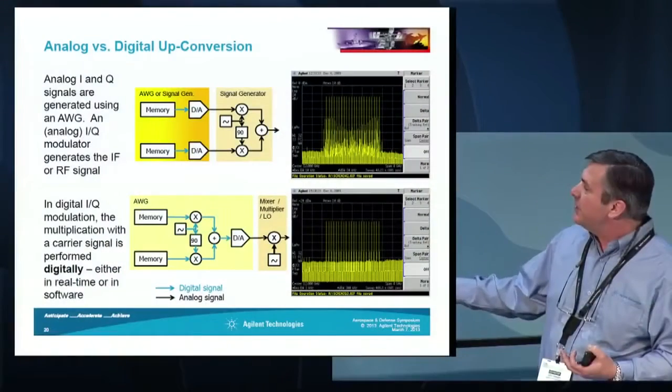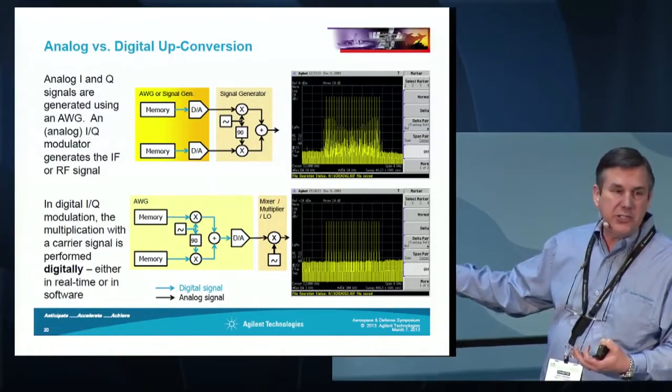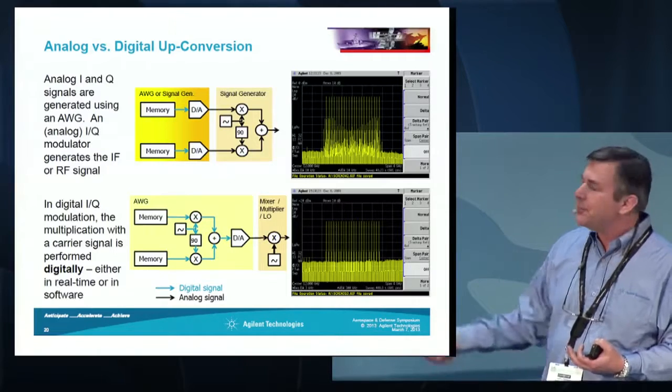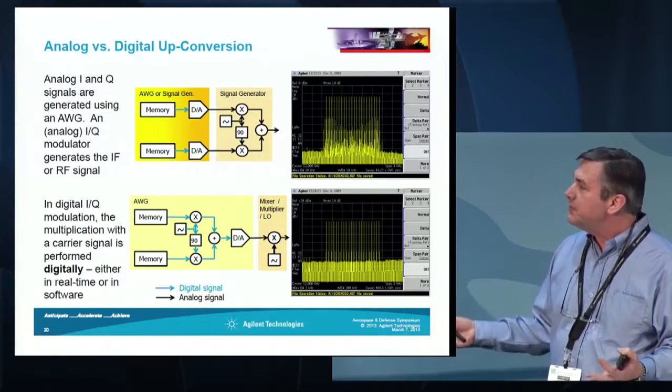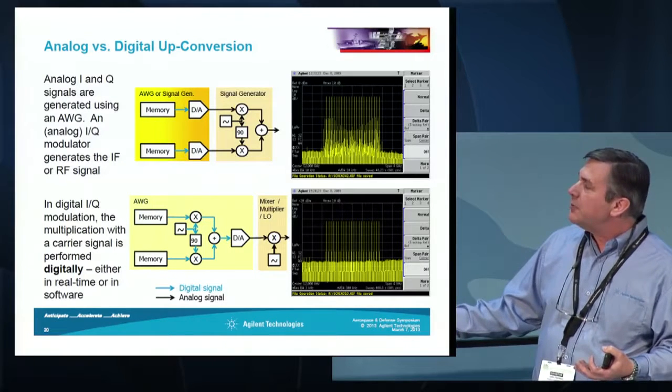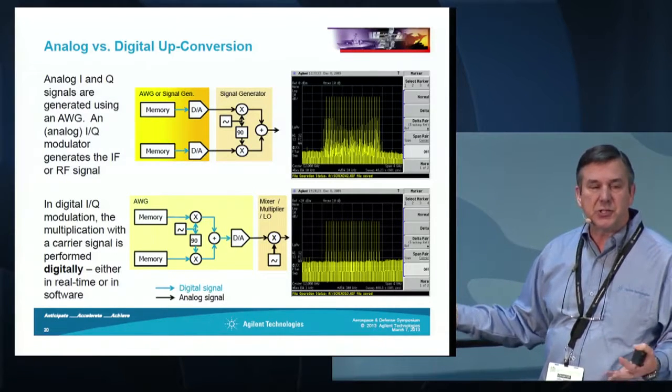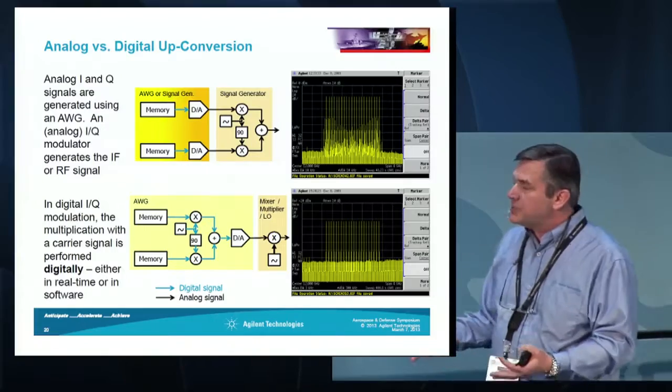It has some problems in upconversion. You have a lot of insertion loss when you try to mix this up. But what you do have at the IF output is a very clean spectrum without all these sins of the IQ modulator. These have gone away. And as I mentioned, what I've just described is done non-real time, and that's a little inconvenient.